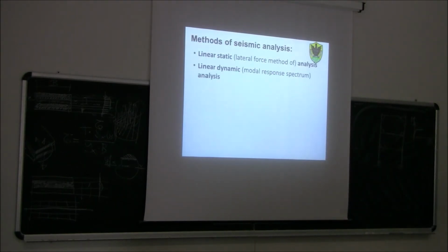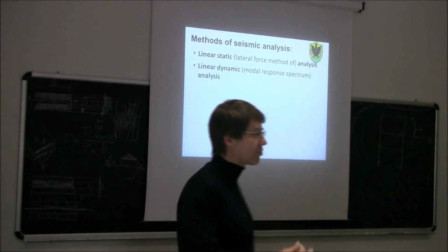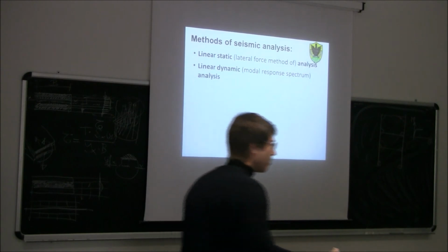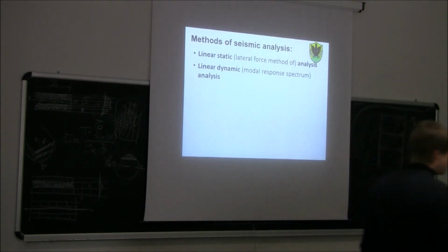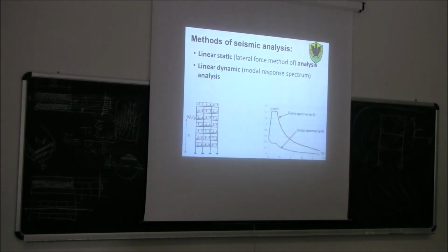Then I have what is called linear dynamic modal response spectrum analysis. We just mention this here, we don't go into details, because this will be dealt with extensively in the course of dynamics of structures that we're going to have next semester. So linear dynamic or modal response spectrum analysis is another method where basically we always start from the design spectrum.